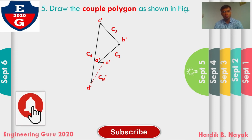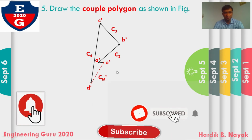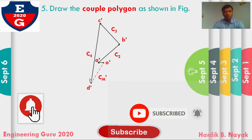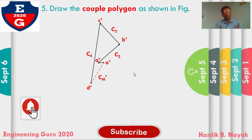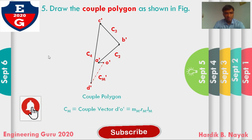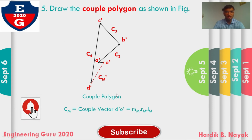Here you can see all the values are taken from column number 6 of the table, and finally this O dash D dash is our closing couple vector, so we can find the balancing couple MM, RM, LM from this couple polygon.